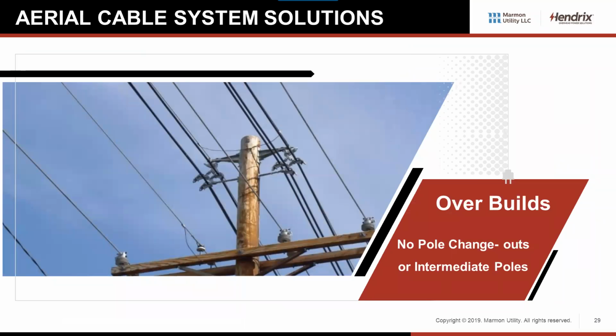We even have some clients that will use existing poles for overbuilds if you're going to build a tie circuit between substations, or if you've got a 35 or a 69 kV line, what you'd call a sub-transmission system between your substations. Again, you have to have enough capacity on the pole, but you can lower the existing distribution down, stringing the spacer cable above it. And again, it'll save you a lot of money and labor from replacing a bunch of poles.